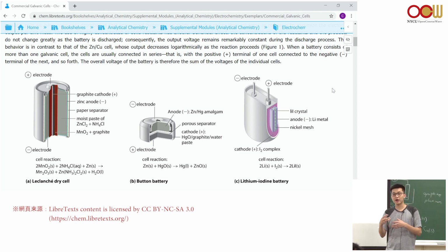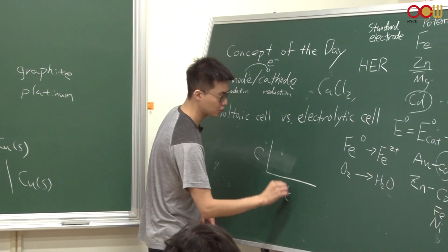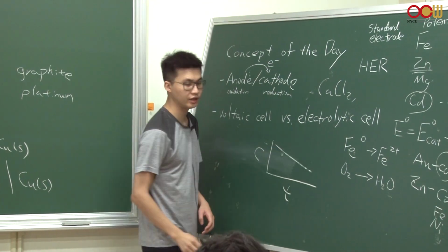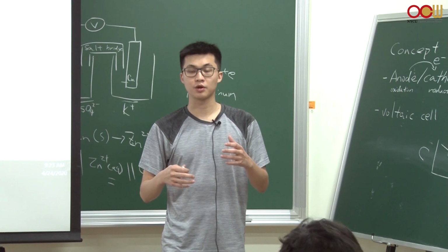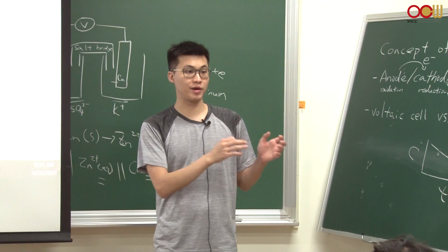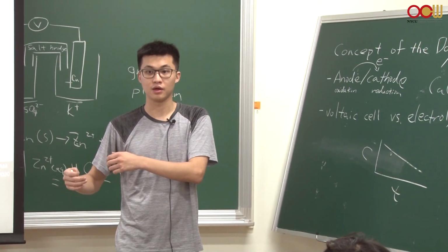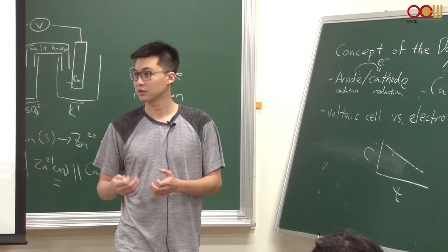cycle. Like I said, the device structure will dictate how well this battery works. And this is why the manufacturer will say how many times this battery can be charged. Generally, the amount of charge that can be stored versus the charge cycle will decay over time. When you charge the battery, you reverse the reaction. However, you did not reverse that reaction completely. So each time, the amount of electrons that can be harvested or utilized decreases.